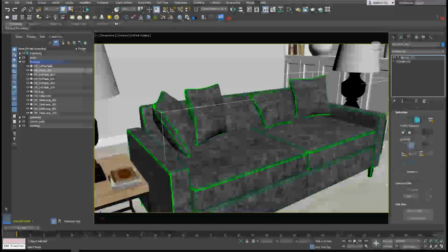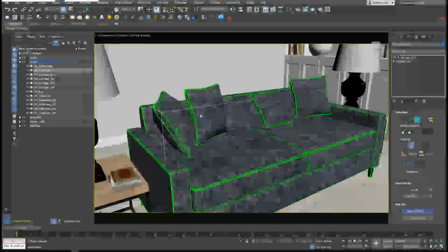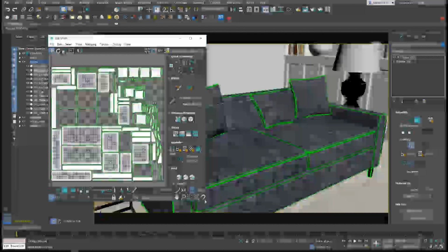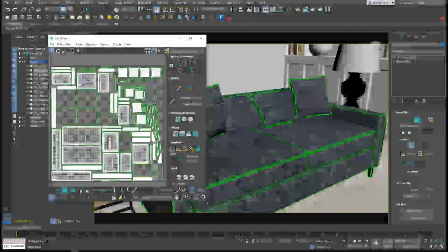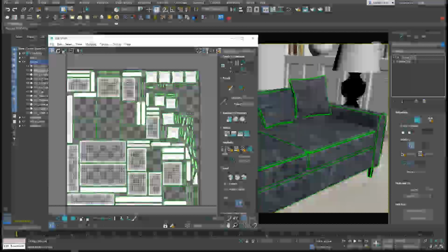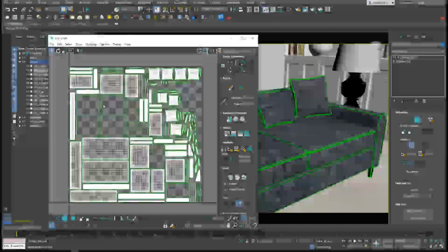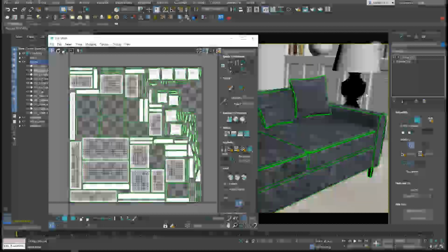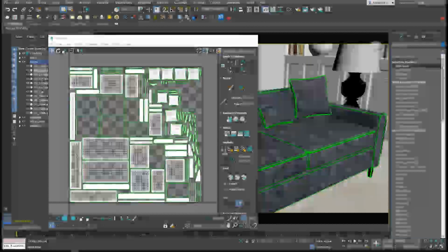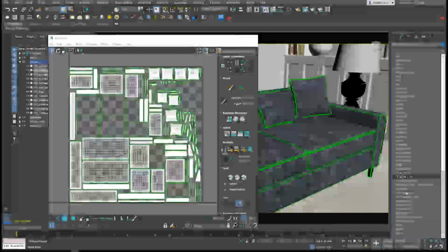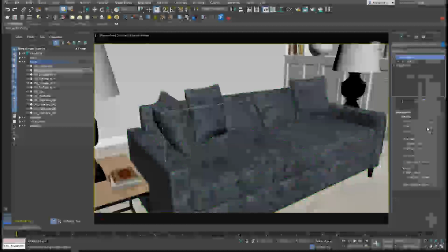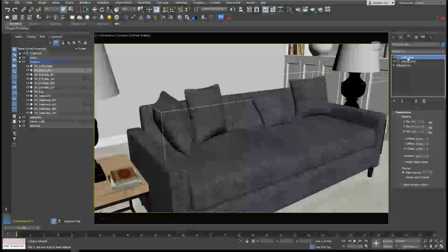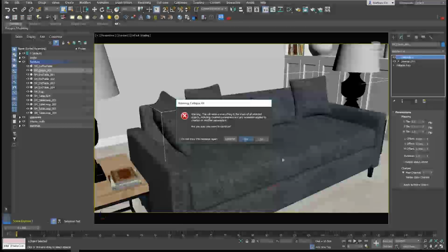Another option for UVs is to create clean, non-overlapping, unique UVs. Those UVs should basically take up space 0 to 1 and, as we said, shouldn't overlap. This is used a lot in video game development where textures are often more complex with lots of baked-in information and non-tileable details, such as pinstriping on a car panel or small graphics on a person's jacket. In this case, the best option is to manually create your UVs using the 3D Tools UV editor. Just be sure the UVs are, again, non-overlapping, have adequate space or padding between themselves and the edges of the texture border, and don't go past space 0,1 on UV coordinate space.